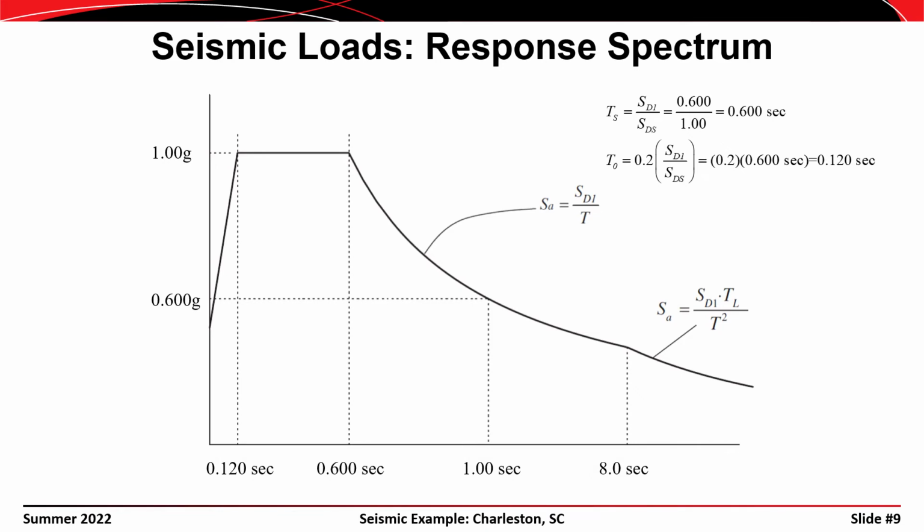Going to our response spectrum for this particular site, we can see that for a period of 0.318 seconds, that corresponds to the peak of our response spectrum, and we would have a spectral acceleration for that structure on that site equal to 1 times G.